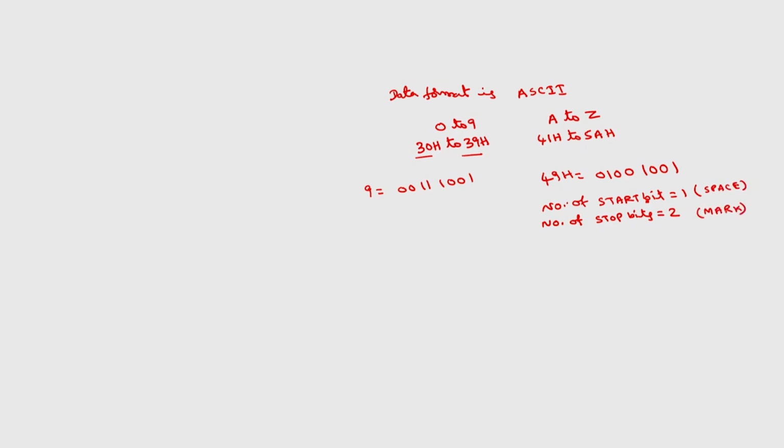So, what is the format that you have to send now for 49H, format of 49H. So, first one is initially without transmitting the data, mark. So, this is the point where I am just starting the transmission of the data. This will be 1 clock period duration. If you assume that this is the clock duration, I will come to this clock duration.